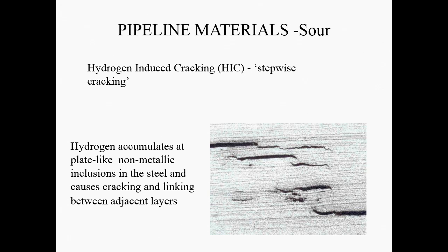And the point I draw your attention to, which is sometimes very obvious as to why these cracks form, is you get this flat crack, and then at the end, the cracks bend up and down. They sometimes call them hook cracks because the crack, at the end of the long defect, doesn't stay in the plane of rolling, it moves out of that plane. So you can see one here, one here.